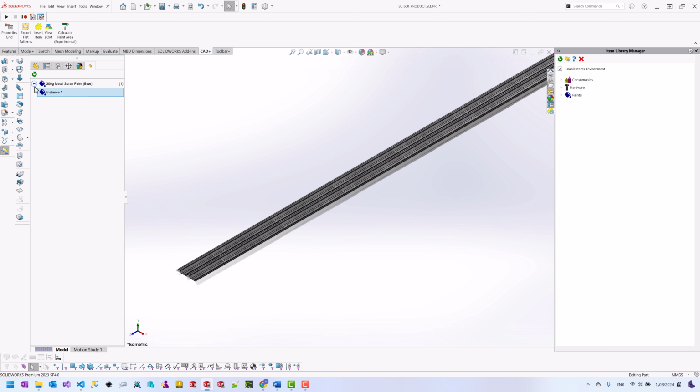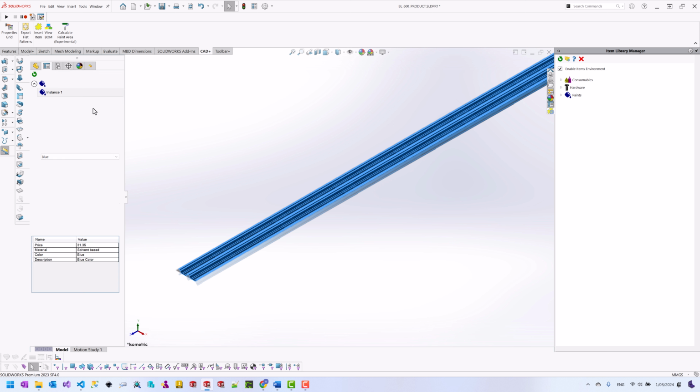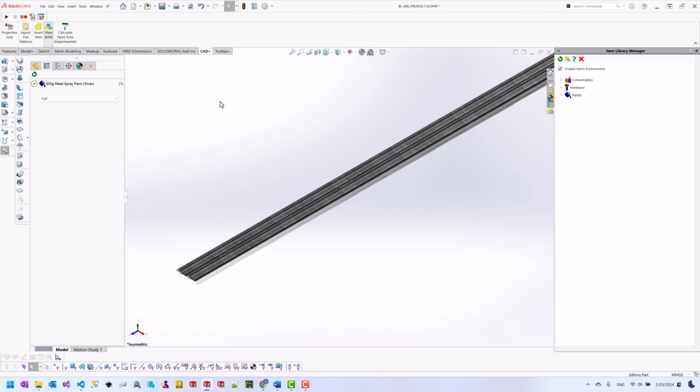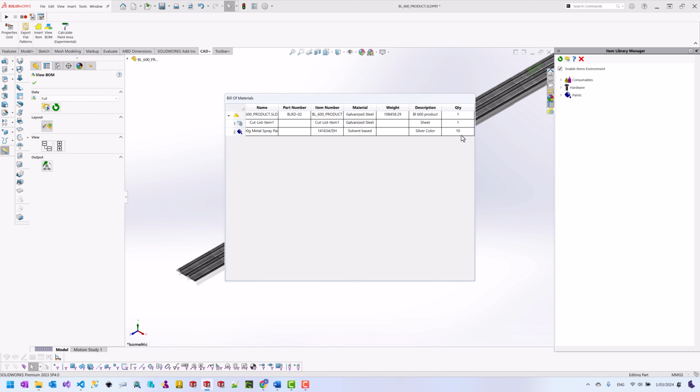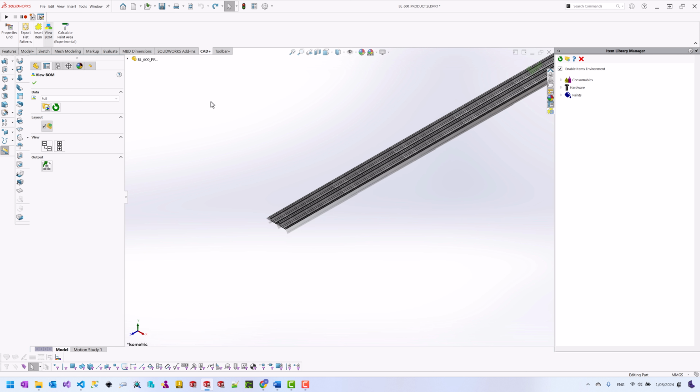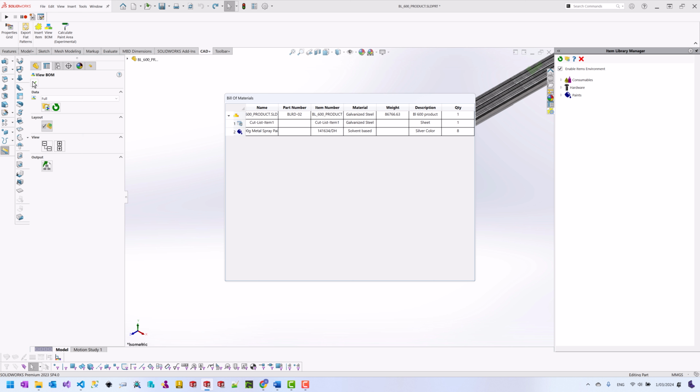If you remember, we have added a new item into our library, so let's change it. So let's go to edit, and now let's change it. Because we have quite a few of these here, I just want to put it to 600. Click on green tick, click on view BOM, and now there's a new item over here, and I need a different amount of that paint in here. So let me just undo the modifications of the model size. So it is back to 12 meters, and if I look at my BOM, that's going to be correspondingly updated straight away.